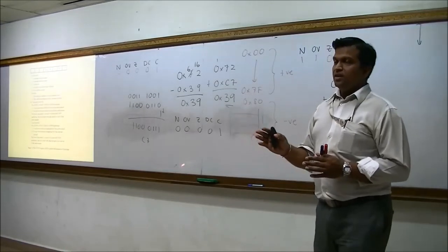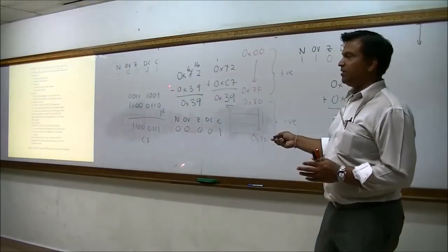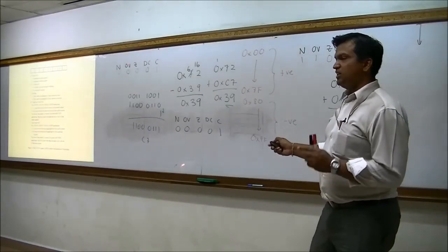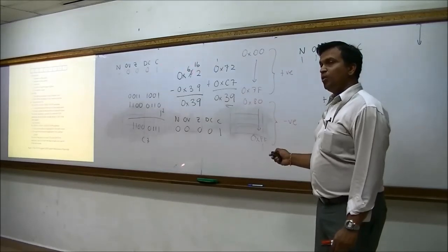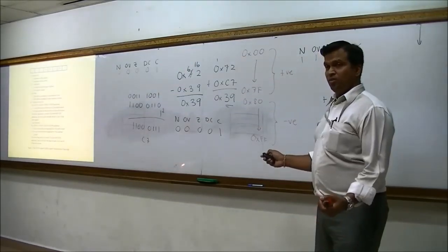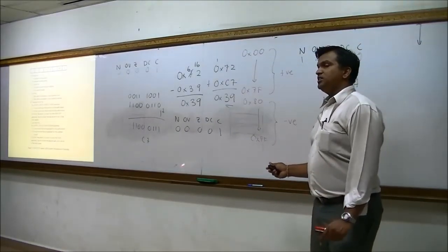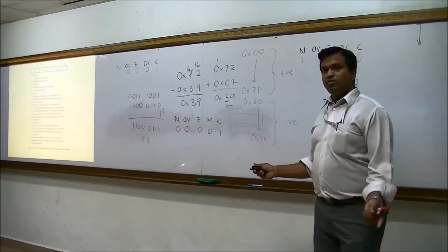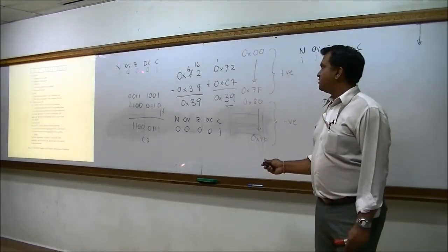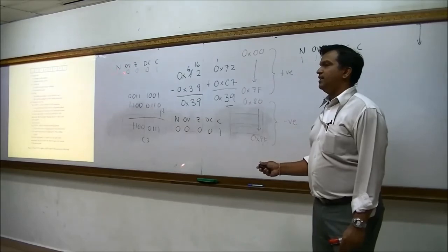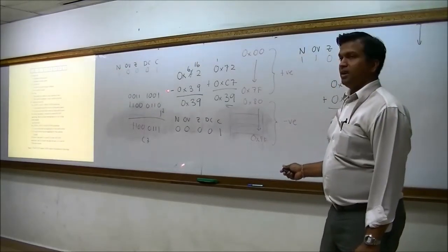Is it okay? Now when you're performing subtraction, these two you have to see in reverse. So if there is no borrow, by right it's supposed to be 0, but we make it 1. If there is no digit borrow, by right it's supposed to be 0, but you make it 1. That means it's reversed, only for that. The rest, the Z, O, V and N, are the same. That is if you're performing subtraction.